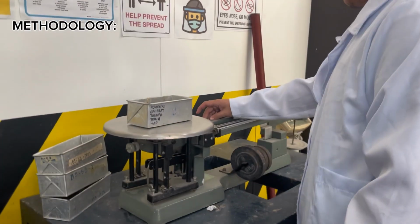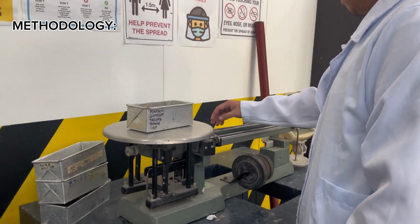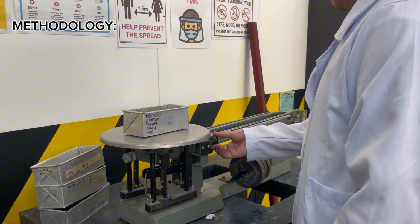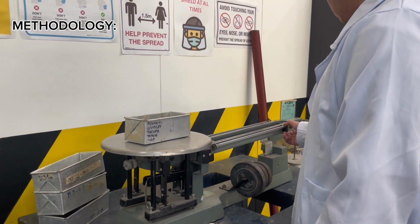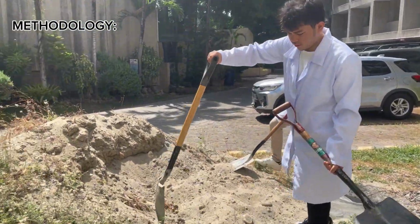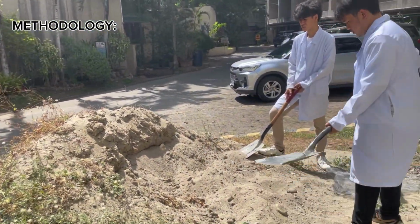For the procedure, we measure first the containers. Number 1, we weigh the empty containers using a scale and note their mass. Number 2, we measure the height, width, and length of the containers. And then, we get the sample size reduction by quartering method.